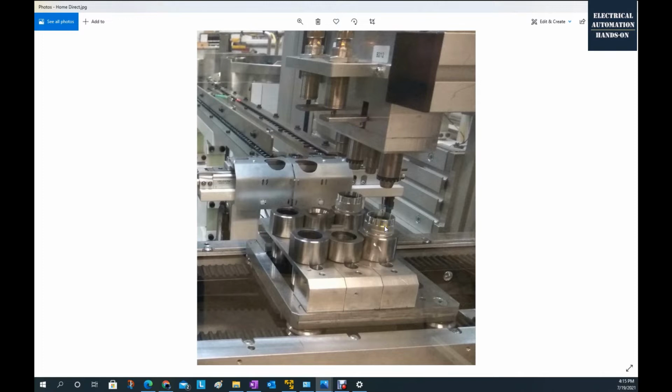In another scenario, if we are using an absolute encoder, at the very beginning we need to preset this absolute position. Or in some cases, some incremental encoders have a battery behind them, so they can retain the value. For those cases, the encoder can save the value, but it does need the first initial value at the beginning. So this MC_Direct can be used for these cases.